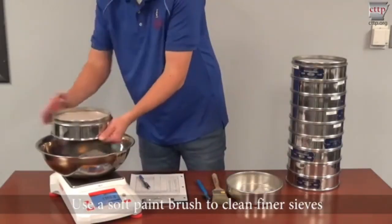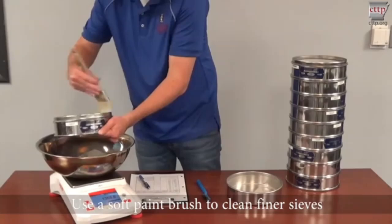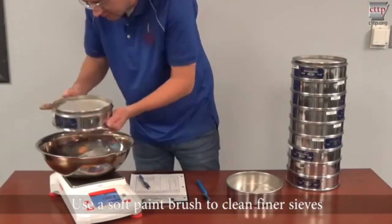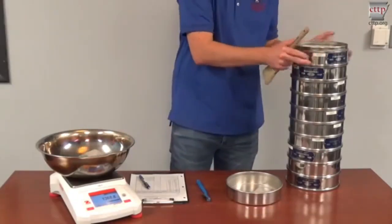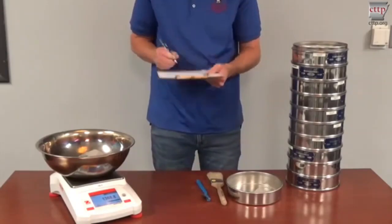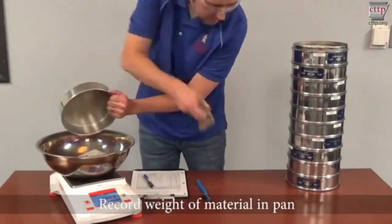Use a soft paintbrush to clean finer sieves. This will prevent damage to the more delicate screens. Finally, record the weight of material in the pan.